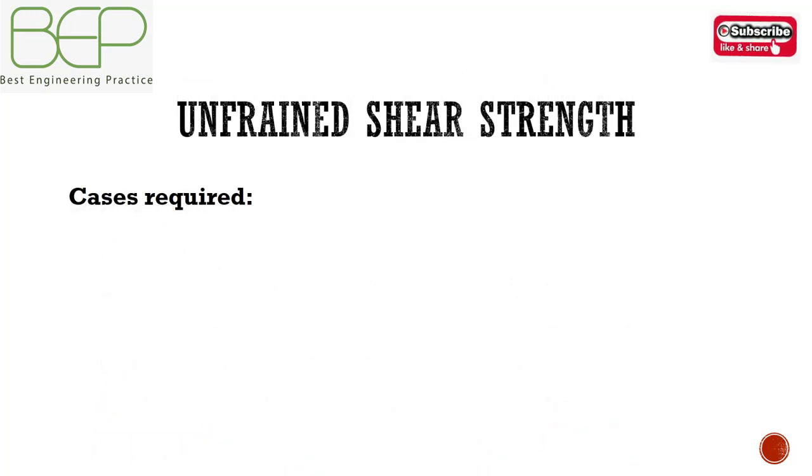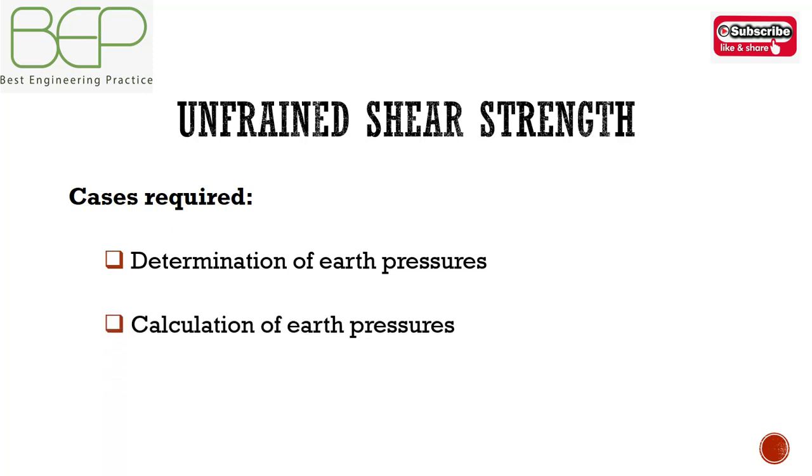Values of undrained shear strength may be required for determination of earth pressure exerted by clays under undrained conditions, the calculation of earth pressure exerted by clays on braced excavations, the determination of bearing capacity, for example, for clay supporting the foundation of gravity walls, and for reinforced earth.